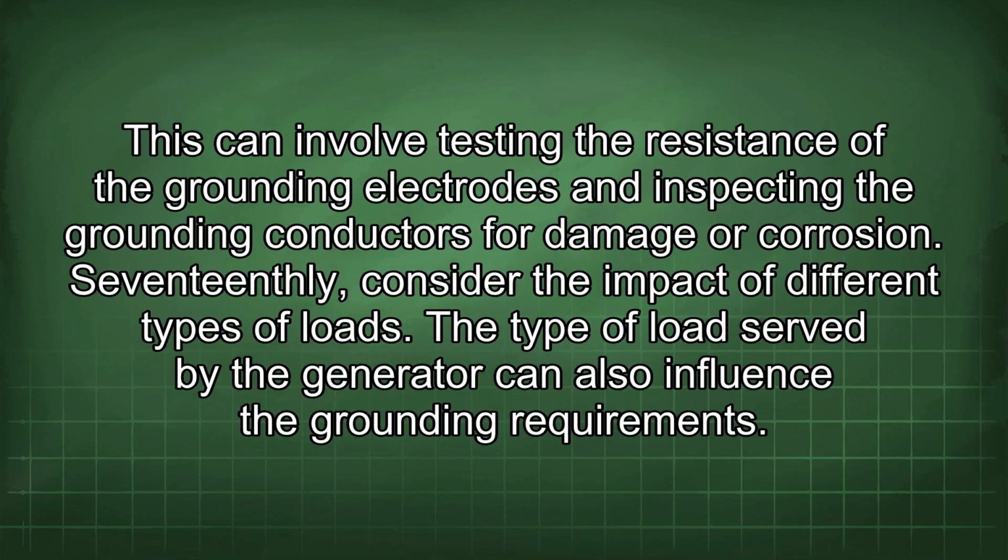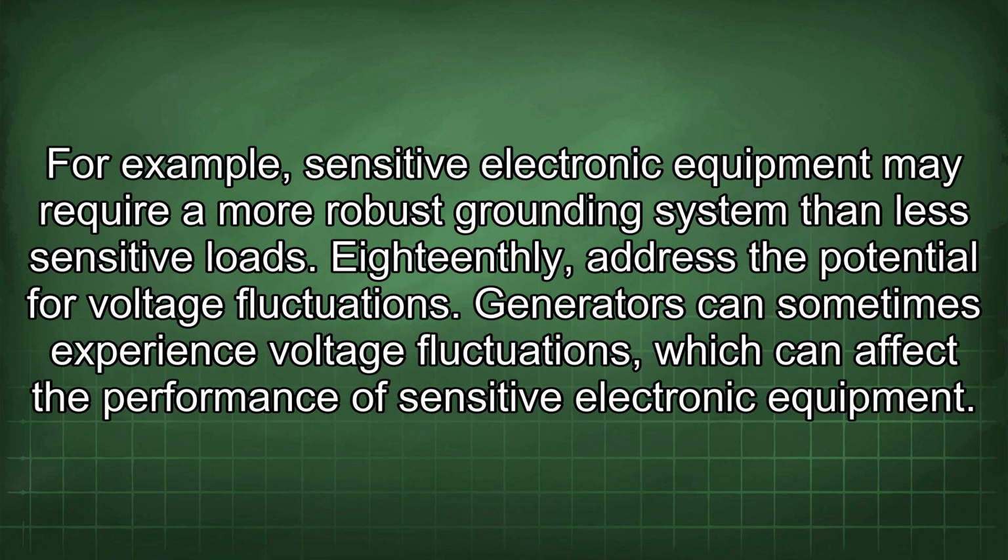17thly, consider the impact of different types of loads. The type of load served by the generator can also influence the grounding requirements. For example, sensitive electronic equipment may require a more robust grounding system than less sensitive loads.